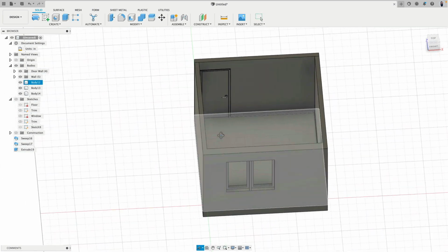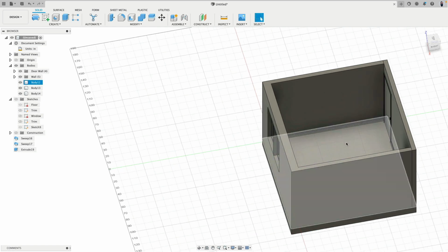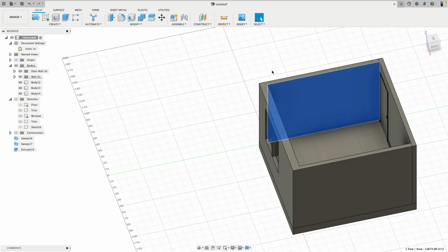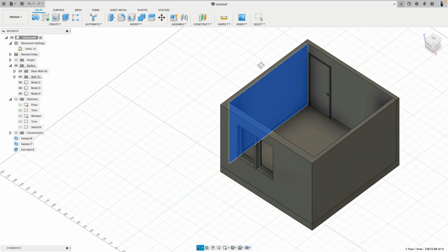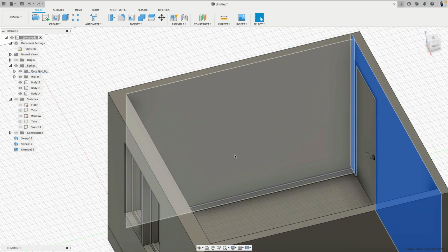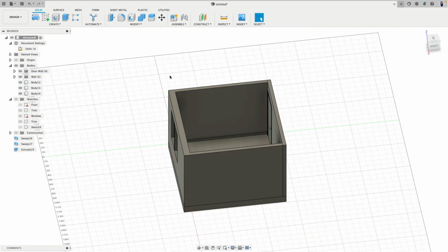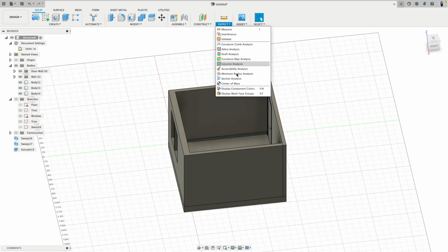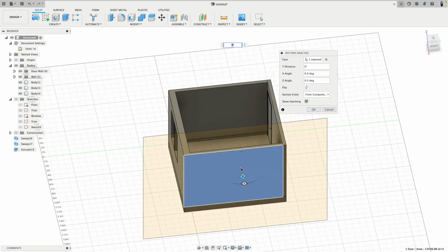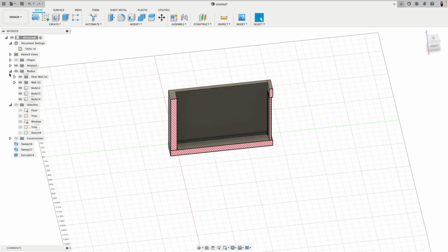So, very good. Now, the last thing to bring this to an end is we would like to add a little bit of simplistic furniture into the space. So here, two dry walls. And then on this wall, very quickly, we would like to put a bookshelf system. So let's select this first. Now it's a little bit inconvenient to look into this space. Let's create a cut section. So we can go to section analysis, bring this back, maybe to here, click OK.